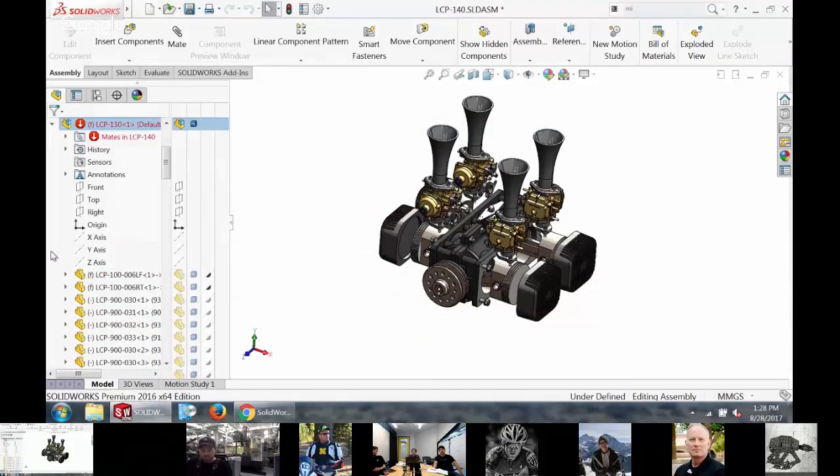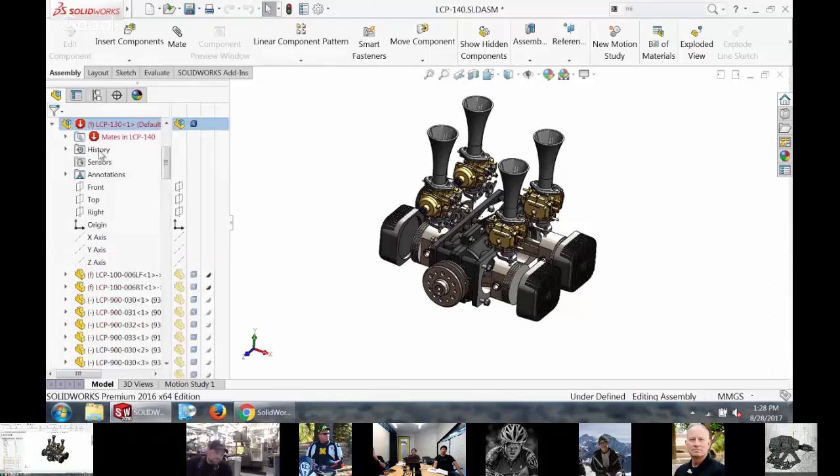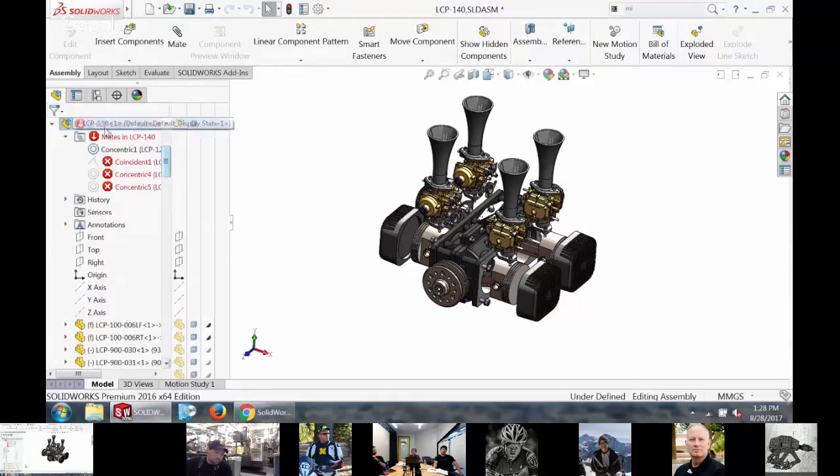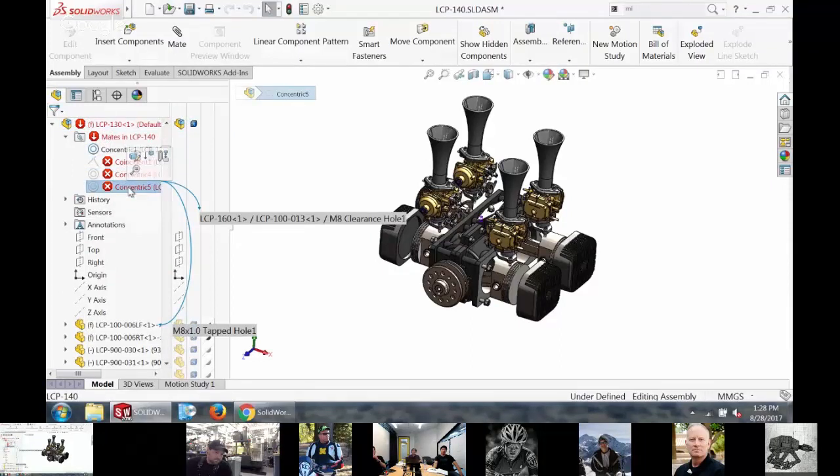If I just open this up, when you see a red dot here, there's some more to what's going on with the iconography, whether it's an X or an arrow pointing down. When it's an arrow pointing down, it means that the problem isn't really with this file, it's something inside this file. So when you hit the expand, then you want to keep looking for the arrows until you find exactly where the issues are.